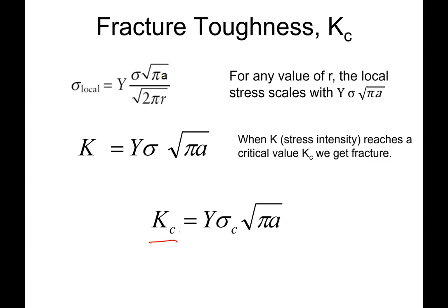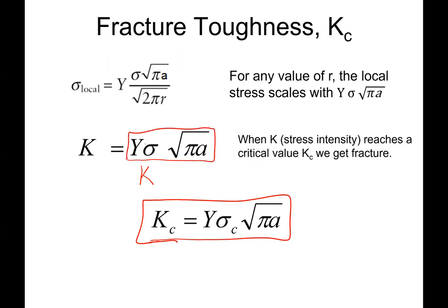Last time we talked about fracture toughness, and we defined our fracture toughness equation. We basically said that when the stress intensity K, given by this quantity here, is greater than the fracture toughness of our sample, then we have a fast fracture. That's our criteria. We're going to need to take a closer look at this fracture toughness value and ask what is the appropriate number to use and in what way do we test our sample for this toughness value.